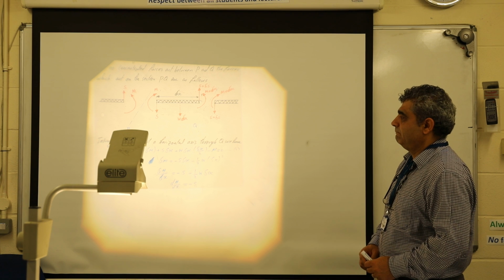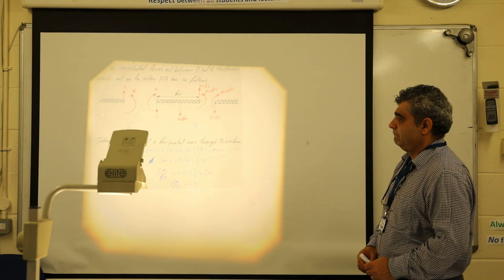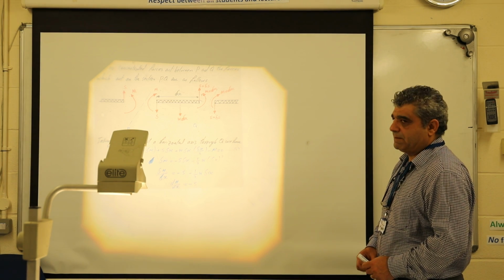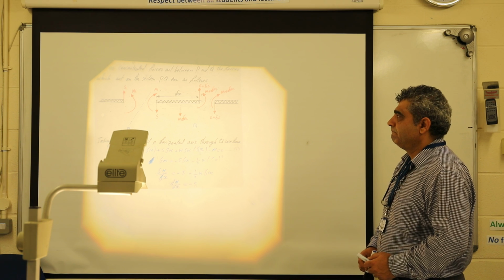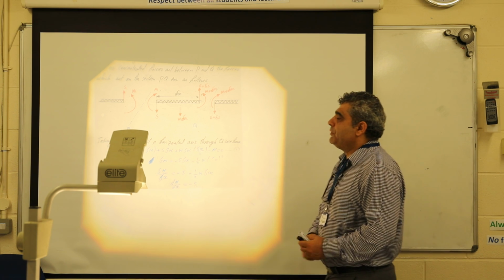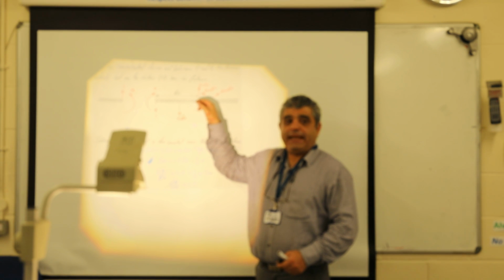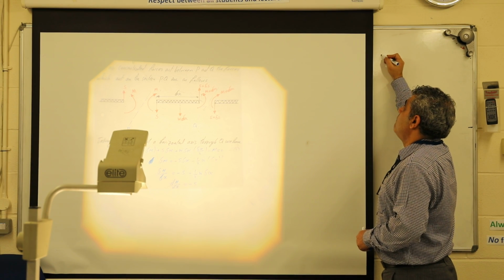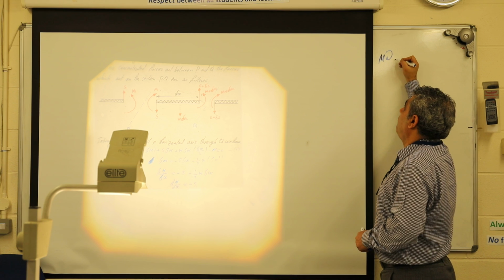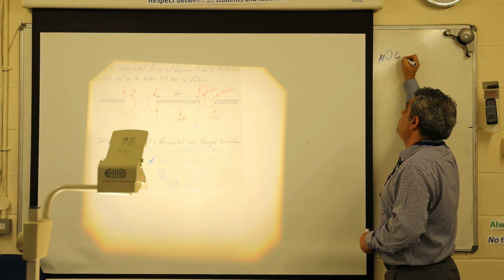Delta x over 2, because we're assuming the UDL to act from the centre. Absolutely. Right. What we're going to do here, I have this piece of beam. I'm going to take a moment about point Q.